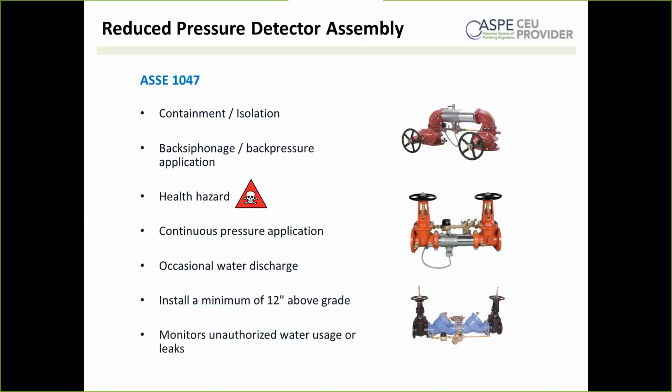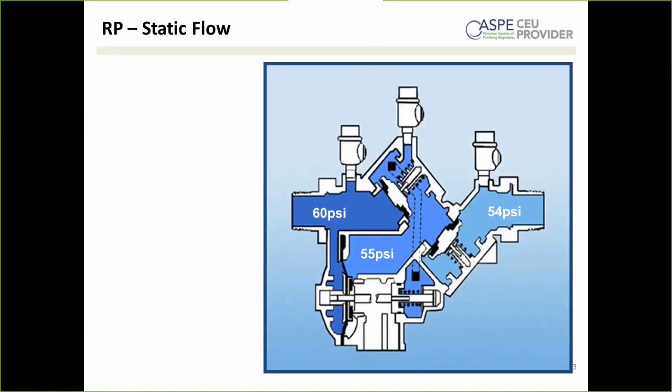So here you see a cross section of an RPZ backflow preventer. Now, how do these work? Like many backflow preventers, the main safety mechanisms are check valves, also known as non-return valves. They allow water to flow in one direction only. As you can see here, we have one check valve that I'm circling with my pointer now, and a second check valve down here.